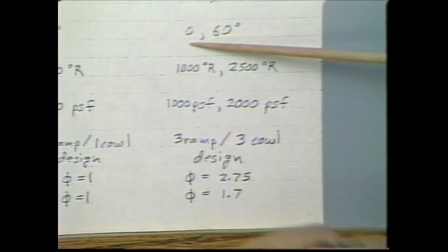Everything above was done fixing the equivalence ratio at 1 and not trying to thermally balance the system. What that means is that a certain fraction of the heat that went into the airframe was thrown away. There was no attempt to cycle enough fuel through there to capture all that heat.